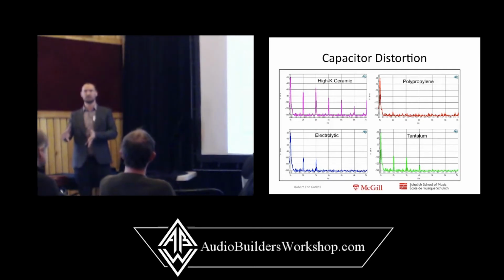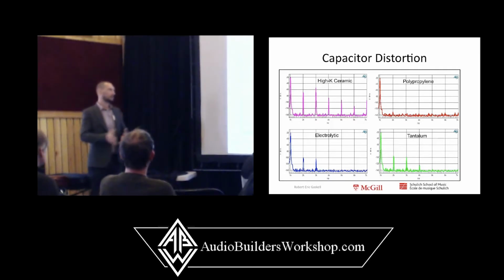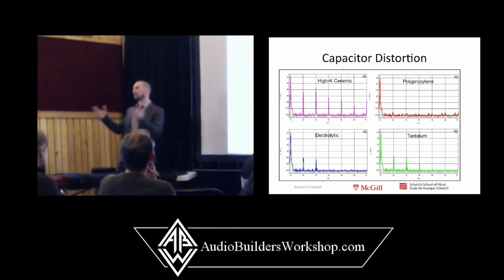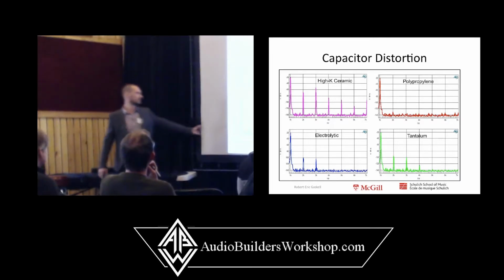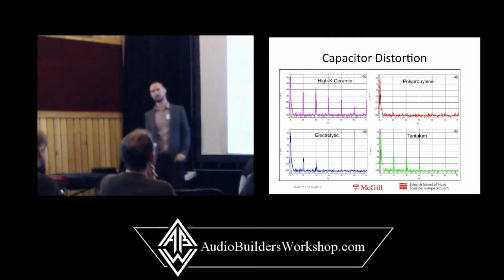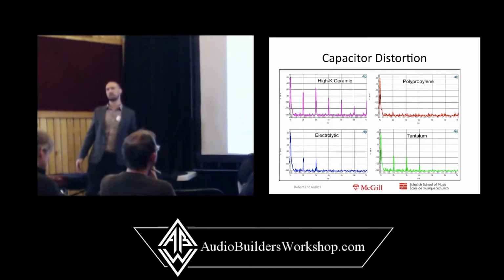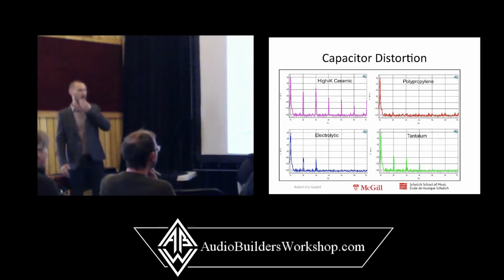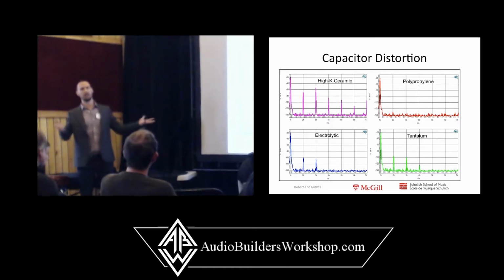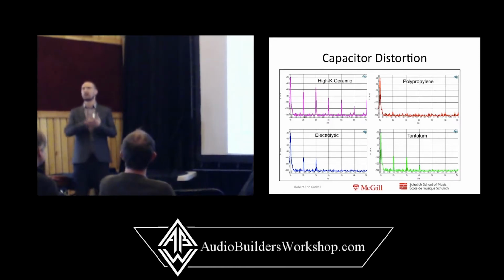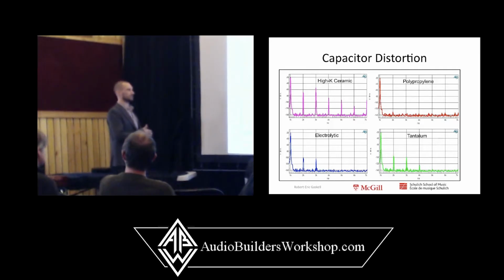One of the reasons I even started researching it was because I was interested in what that means for a mic pre that uses phantom power and electrolytic capacitors to block that DC. Does it sound different when phantom power is on versus off? Because I could see a distinct difference in the amount of second harmonic distortion produced with and without the DC bias.